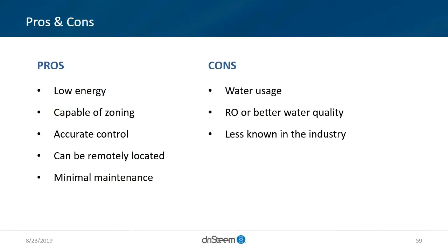So really the takeaways from this presentation, and then I will open up for questions. It looks like I have 5 remaining that I have not addressed. So pros and cons. The pros: low energy usage. All adiabatic technologies, including high pressure atomization, are lower energy due to the fact that they use energy in the air to evaporate the water.